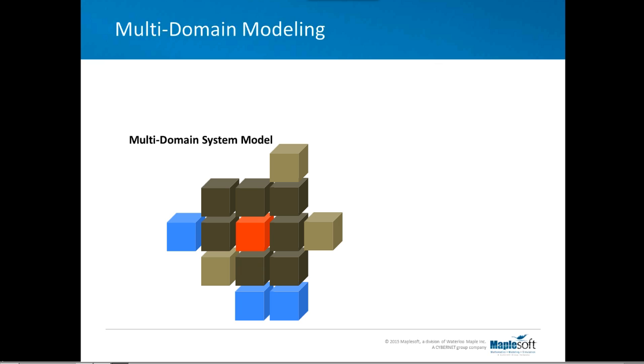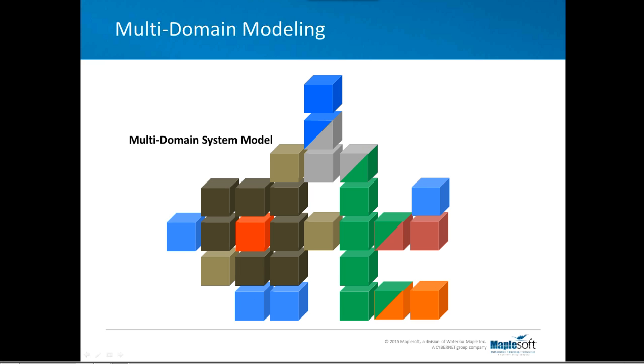Let's look at some examples, but before that, I just wanted to bring this point to an end: considering a multi-domain system, we just looked at the multi-body components and joints and visualization and some signal blocks. Then through the use of transformers, we can connect that to other domains, like we connect the revolute joint to a 1D mechanical, and then through an electric motor, we connect it to the electrical domain. Or through a rotary to translation joint, like a gear pinion, we can connect rotary then to translation. Or go from prismatic to translation, and then through a hydraulic piston, go to a hydraulic domain. So that's how your model gets connected and becomes bigger.